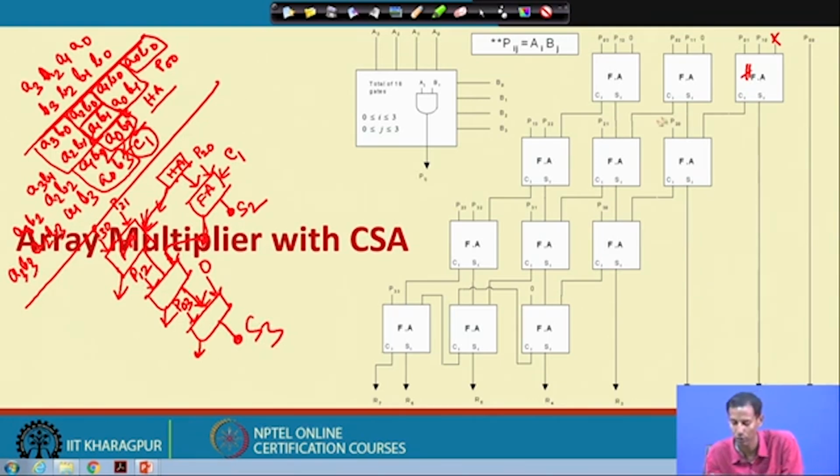Okay. So, here you see that this is the half adder case, or this also is a half adder case, then that carry is generated for the full adder. Here P20 is considered in this case along with the sum from this and the previous carry. So, it is generating S1 as well as producing 2 carries.